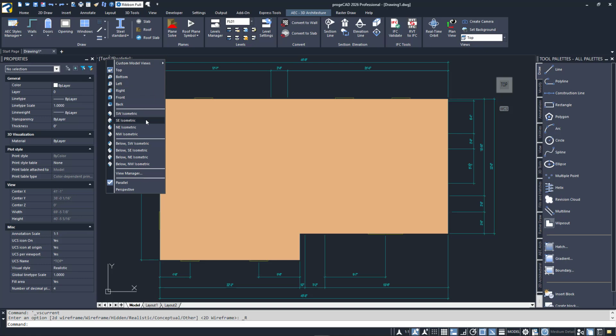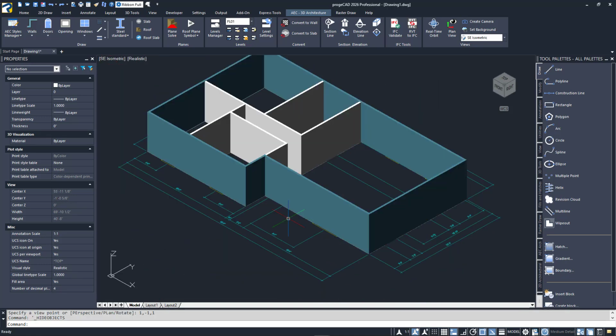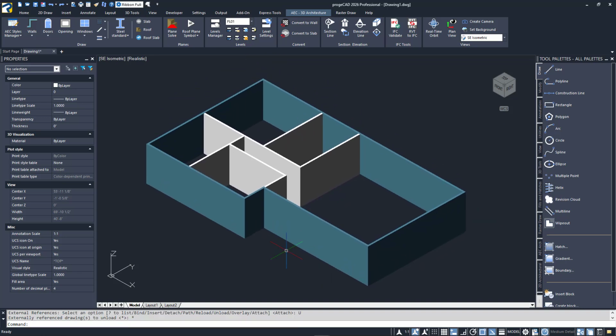Now, we all know that during the design process, things change. So far, I've used the supplied generic wall styles, but what happens when the architect comes back and tells you that the exterior walls should be a 4-inch stud with a 2-inch air gap, sheathing, and a brick veneer? You certainly don't want to erase it and redraw. There is an easy fix for this.